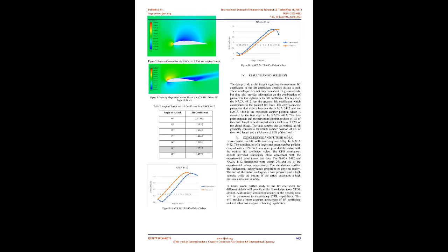The mesh is a significant part of the simulation because the finer the mesh is, the more accurate the simulation is. The mesh is divided into many cells, and the governing equations will be solved at every cell. Therefore, around the edge of the airfoil, the mesh will be finer than in other parts throughout the flow domain to understand the aerodynamic behavior along the airfoil. This study accomplishes this through adding 10 layers of cells around the airfoil, with each layer containing 250 cells, shown in Figure 5.